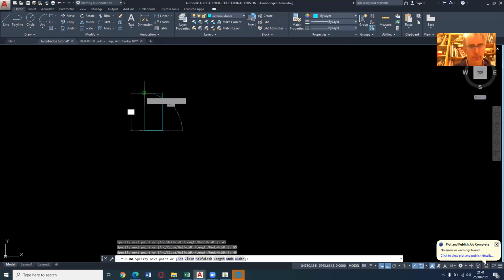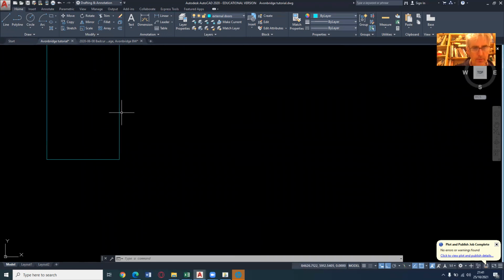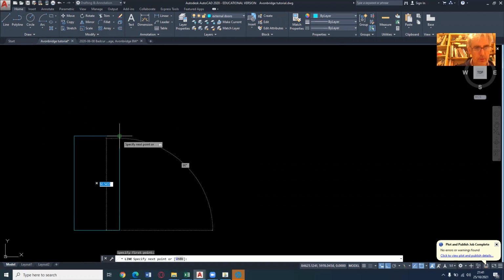In other words, it's a 45 by 95 rectangle. And I want to leave maybe a little bit of a gap in between, just a little bit of tolerance so that the door edge is not scraping against the frame. I'll maybe offset that slightly by a couple of millimeters.